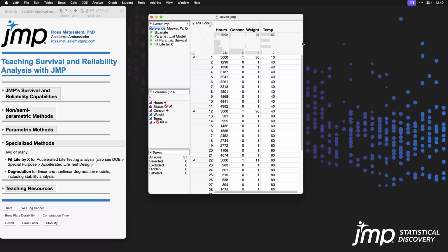If you're not familiar, in accelerated life testing, we take an acceleration factor, let's say temperature, and we use it to induce failures in something in a shorter amount of time. Because if we tested things under their standard operating conditions, they would take forever to fail. So if something would take 100,000 hours of operation to fail at normal operating conditions, we can't really reliably gather a lot of data in a reasonable amount of time. But if we crank up the temperature, maybe they'll fail much faster. Then we can build a model that relates temperature to the failure distribution, and then use that to go back down to normal operating conditions and see what the failure distribution is likely to look like.